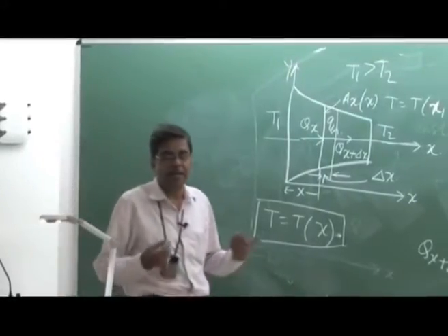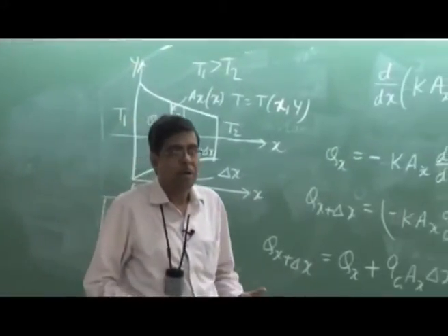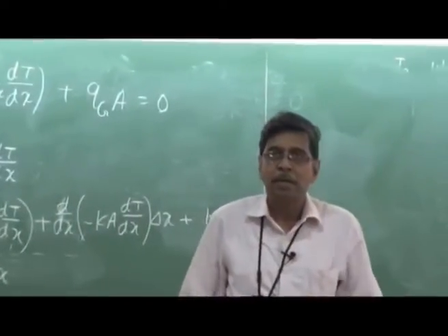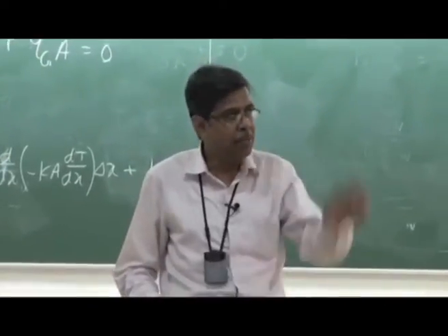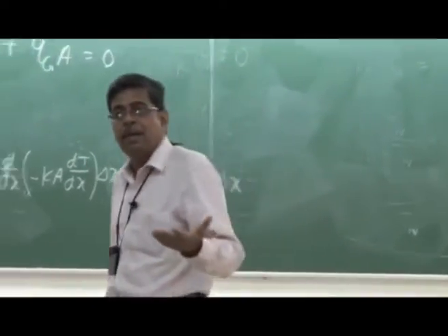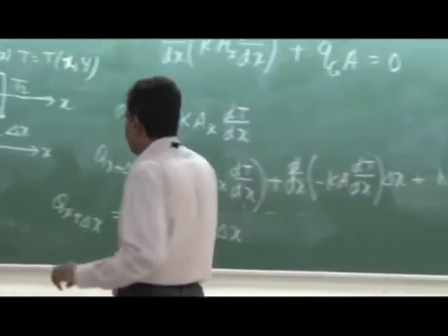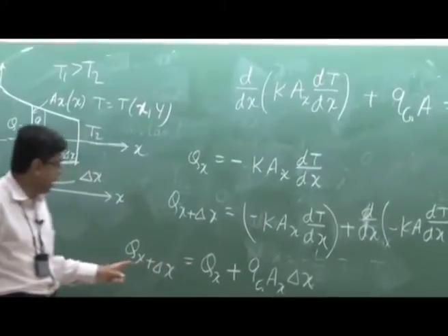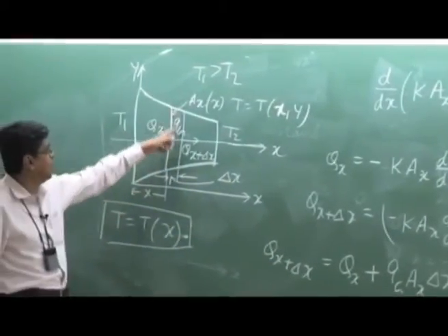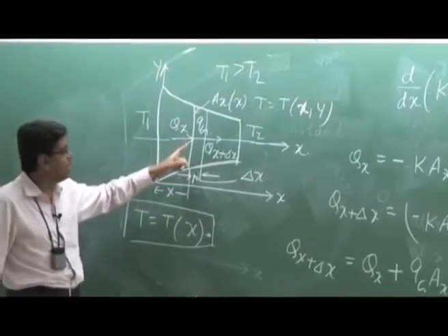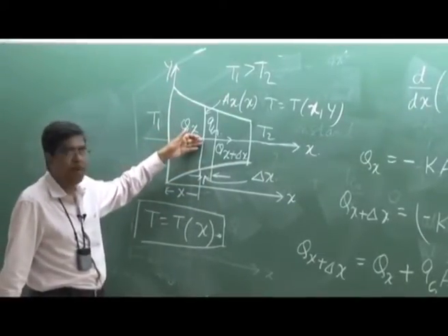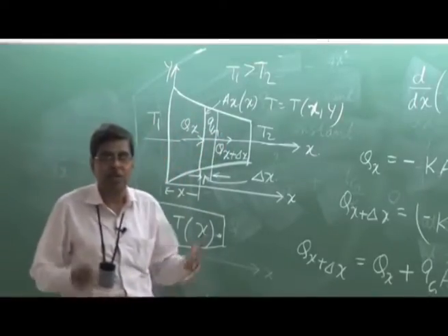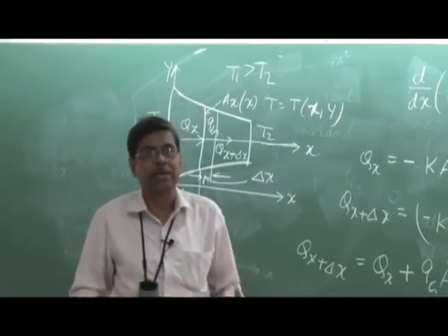This is my derivation of the general heat conduction equation, or for the one-dimensional simple heat conduction equation for your purpose, the procedure is the same. Make an element, take the energy balance by describing the heat flux by the Fourier heat conduction equation. And in the energy balance, we have not considered the change in internal energy, because it is at steady state. That means energy coming in and energy going out must balance with the energy generated, so that no energy may be accumulated or depleted within the element.